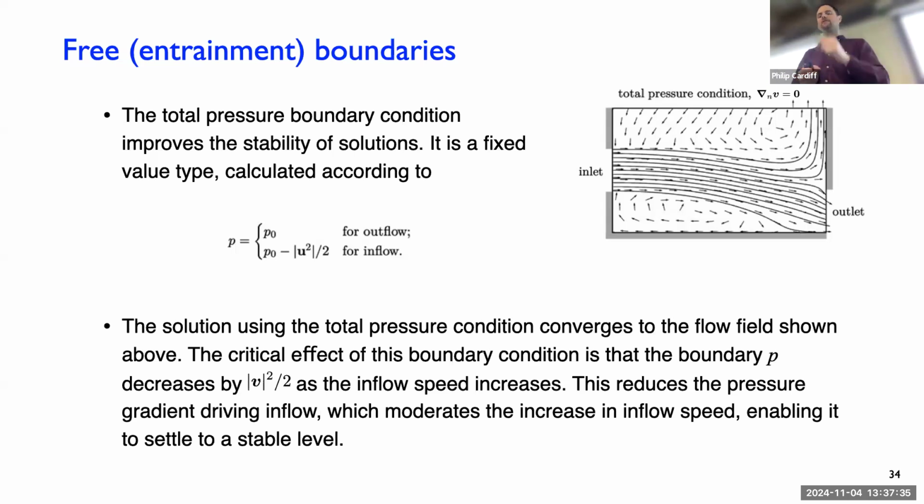There is, in OpenFOAM and Fluent, something called inlet-outlet. The most basic setup is you have an outlet, and if the fluid tries to change direction, it will just switch to a wall. So if fluid is going out, that's fine, it's fully an outlet, and if any face of the mesh starts to come back, it just turns into a wall, so it doesn't let anything back in. I think they're called inlet outlets. So just so you know, that's what happens. If that's not representative of what happens in your case, you might get strange pressures at the outlet where suddenly the wall appears, or it might be unstable if walls appear and disappear.